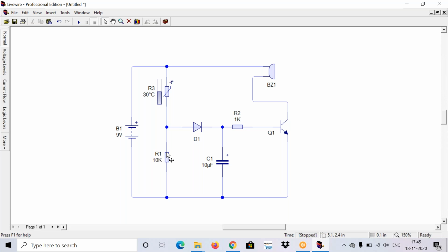Now if I run the circuit, you can vary the temperature here because this is a manual process of varying. If you consider a digital sensor, then it will take the values directly. Because it is a simulator, we need to change the value with our hand. You can decrease and increase the temperature value like this. Go to the bar which is present to the left side of your thermistor. Place the cursor over it and drag it from top to bottom to change the values.